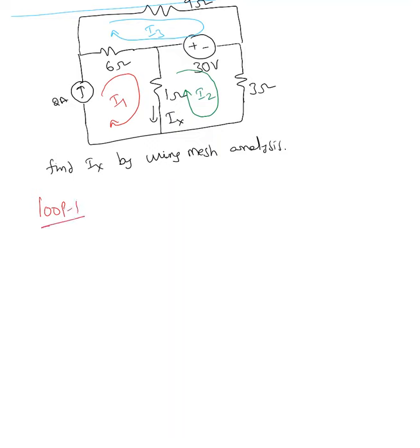check for any current source in the outer branch of that loop. So for sure I have a current source at the outer branch here, so I can take I1 equal to 2 ampere because my assumed direction and the real current direction are the same. So that's the reason I1 equals 2 amperes. Anyway, whenever you look at a current source, the head is always positive, tail is always negative. Just want to give you that for reference.